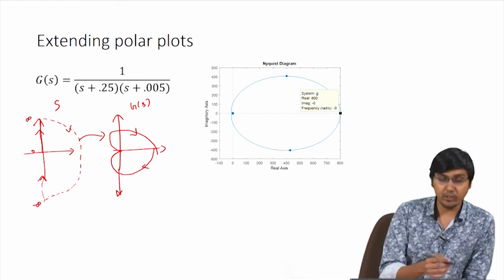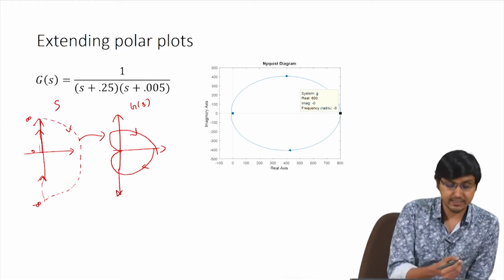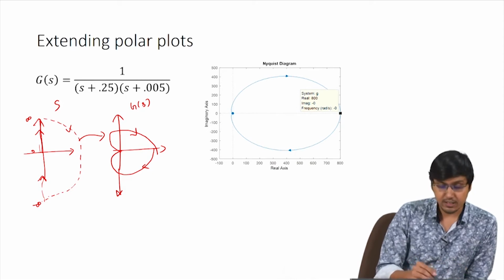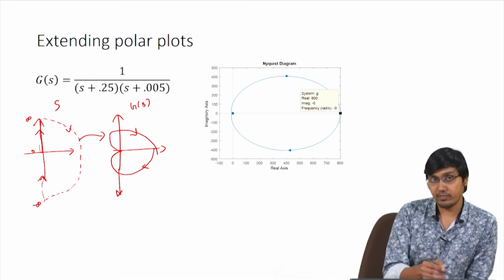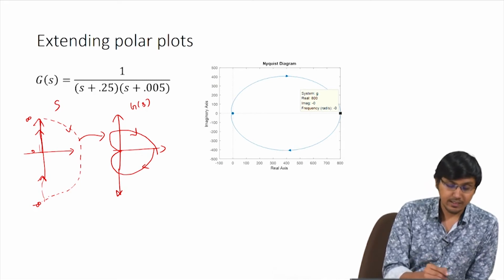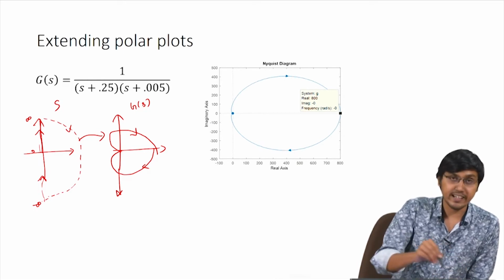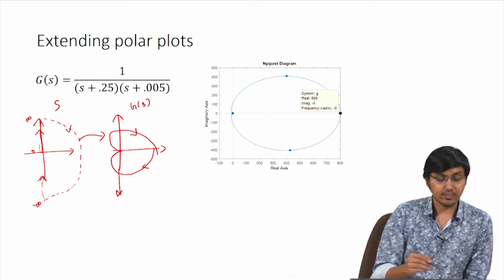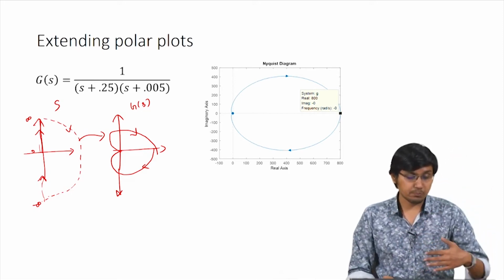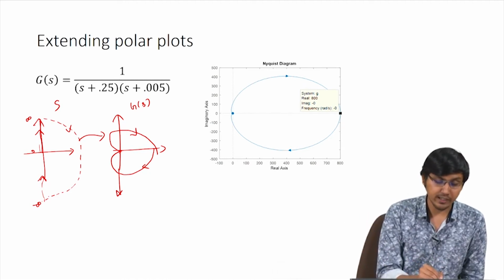So you can intuitively feel that this line is omega changing from 0 to infinity, and this is omega changing from minus infinity to 0. So basically the angle alone changes for every omega, and at r equal to infinity, this is an infinite radius, you are actually covering the entire S plane when you go via infinite radius, and that actually boils down to a point here.